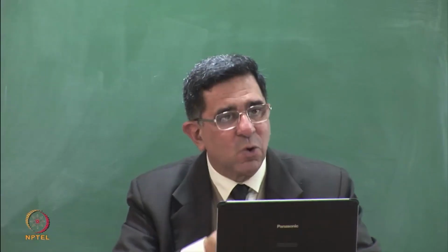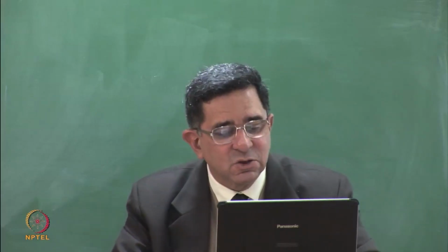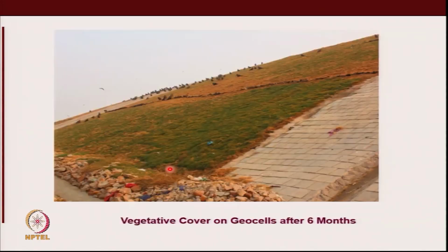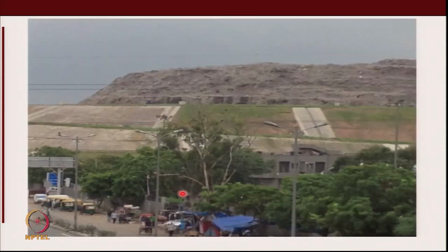You can fill soil in it and hold it. Put a geogrid. You can see geogrids at the bottom, and that's the geocells. That's the rock toe, and that is the finished slope. And these are the drains which are taking the water down. These are paver blocks. These are geocells with soil.